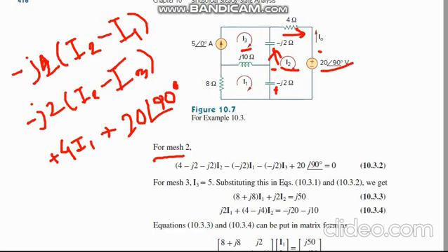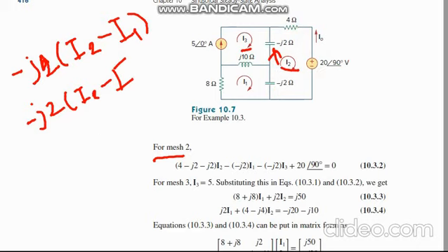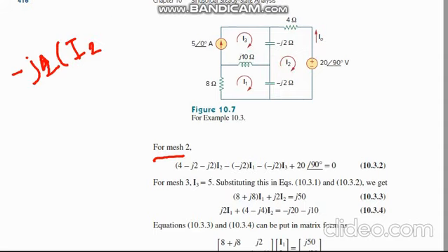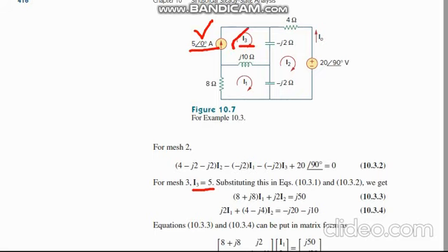Okay. Similarly, you can do the other equation in I3, but there was a current source. So first of all, recognize the current source. As you know, mesh analysis determines the current. So here's the current I3. First of all, take I3 as 5 ampere in loop 3, because this current flows in this loop. So I3 is equal to 5. That has been determined.